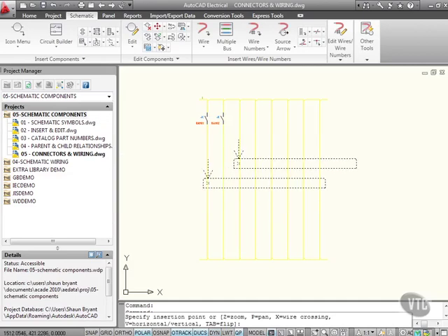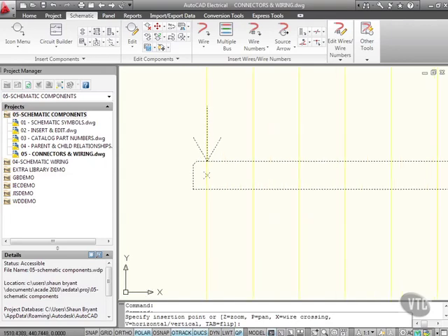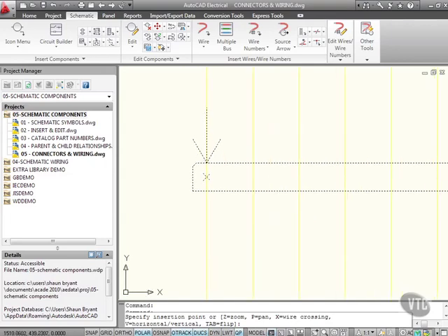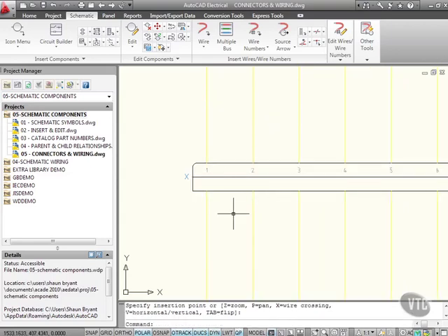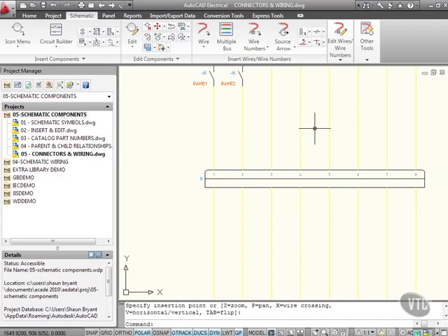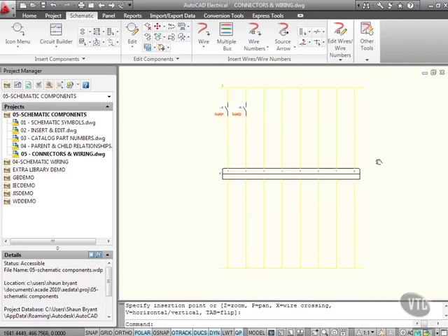And as you can see, there's my connector block floating around. I'm going to position it just there on the first rung of my circuit there. I can even zoom in a bit if I want to. So there we are. Get that arrow nice and neatly and click. And as you can see, everything links together. You'll notice it cuts the wires for you, and that's all linked up now with that connector.